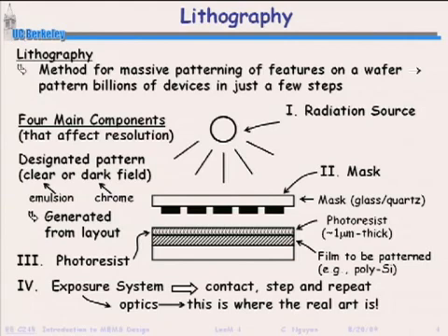In addition to this process, the other important thing is some kind of photoresist. Okay, so this is some kind of resist material that's sensitive to light that can be patterned by that light. And then what you can do is etch whatever features you pattern in your photoresist into the layer underneath it. Okay, that's what we're trying to do. We're just trying to pattern a photoresist so it creates the pattern we want. And we really want that pattern in the film under the photoresist. And so we'll etch that film. The photoresist hopefully will protect that film from the etch. Any exposed places will be etched.